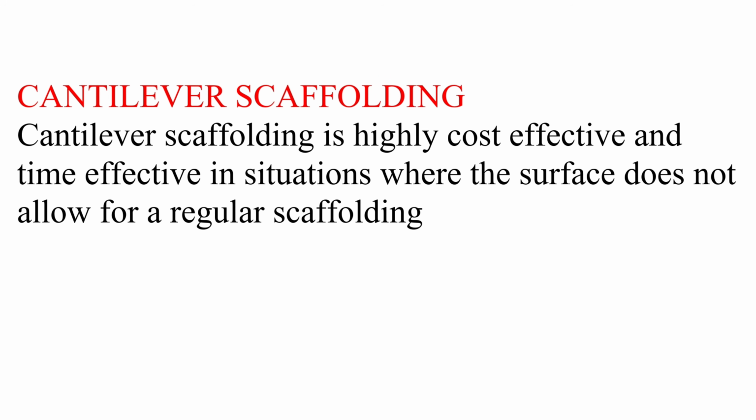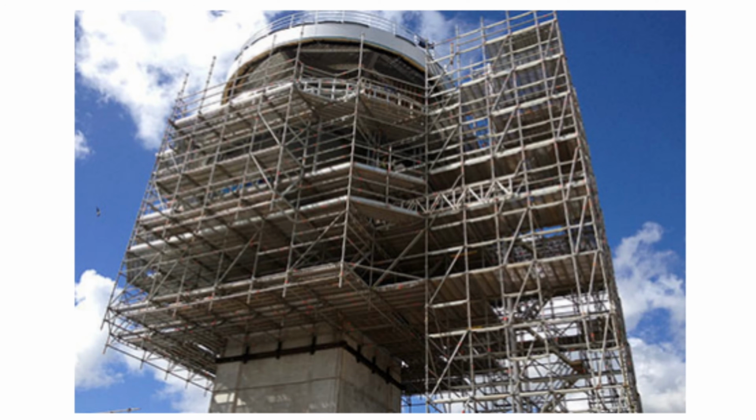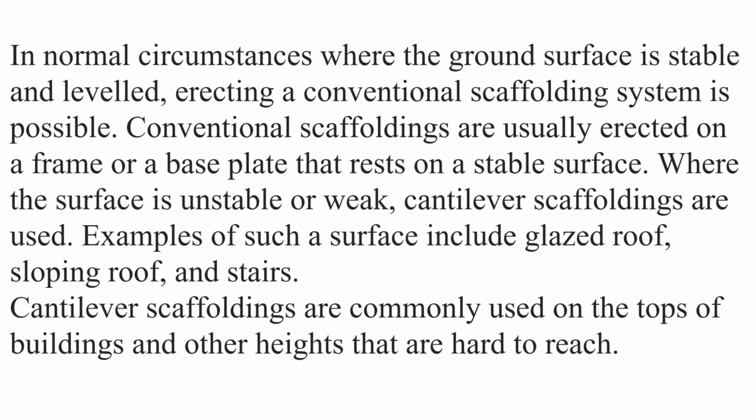Cantilever scaffolding. Cantilever scaffolding is highly cost-effective and time-effective in situations where the surface does not allow for a regular scaffolding. In normal circumstances where the ground surface is stable and leveled, erecting a conventional scaffolding system is possible. Conventional scaffoldings are usually erected on a frame or a base plate that rests on a stable surface. Where the surface is unstable or weak, cantilever scaffoldings are used.